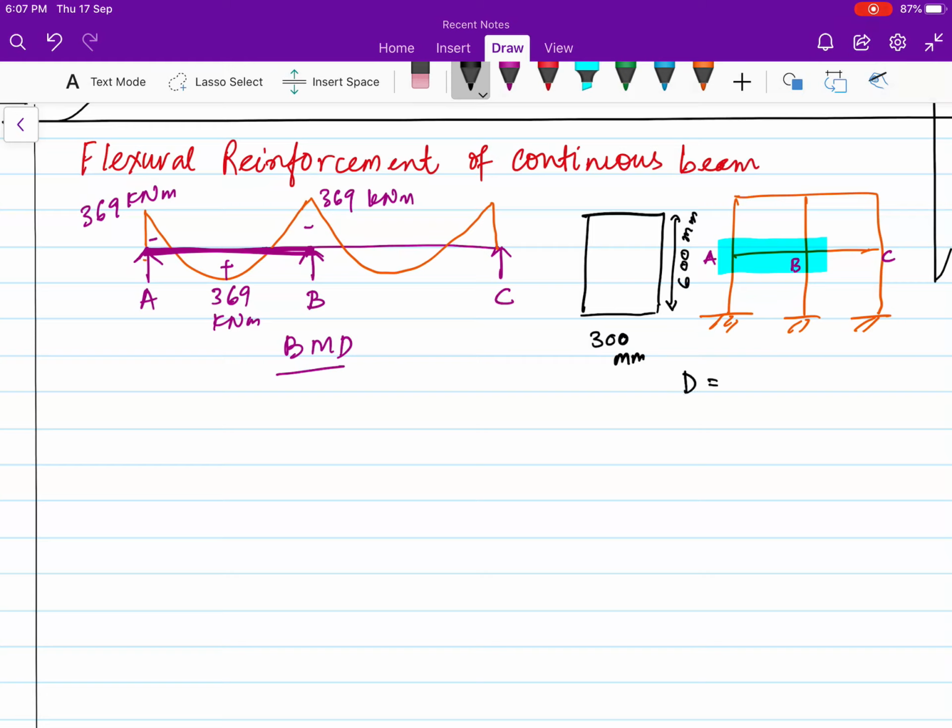So your overall depth is 600 mm, and let's take the effective depth. So 600 minus cover 30 mm minus, if we are having a stirrup, there will be a stirrup also, and then there will be bars. So the stirrup 8 mm I'm reducing, minus 20 mm bar, we can have two layers also, and because the effective depth is from the center of the reinforcement, so minus 20 by 2. So two layers of reinforcement I have taken.